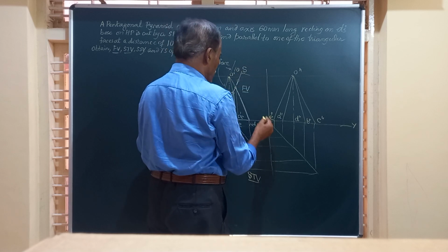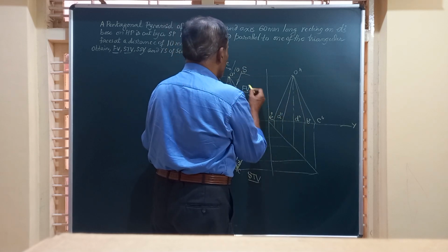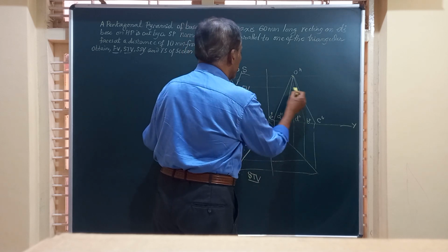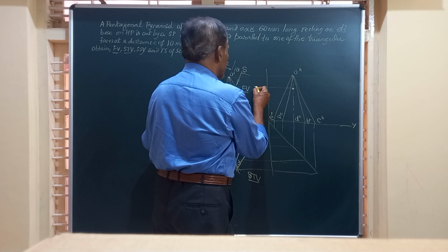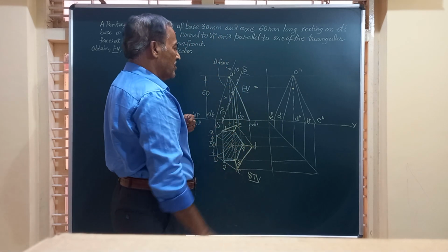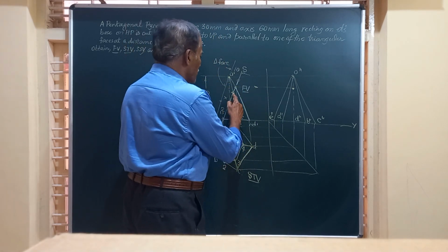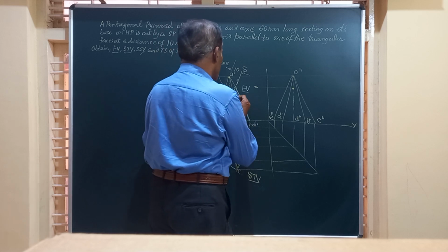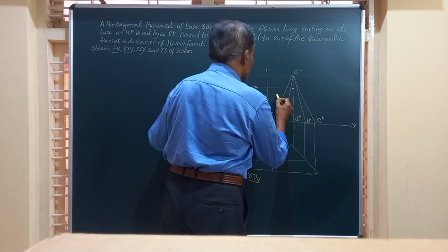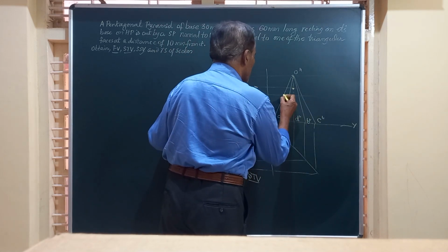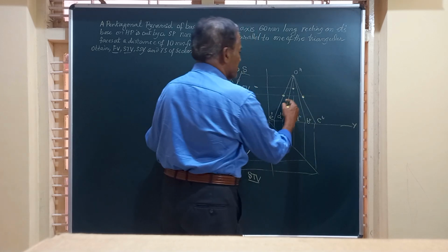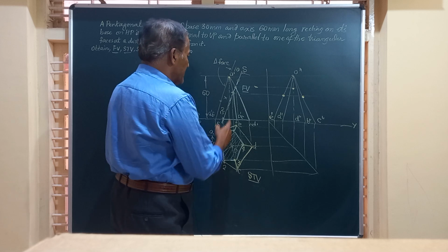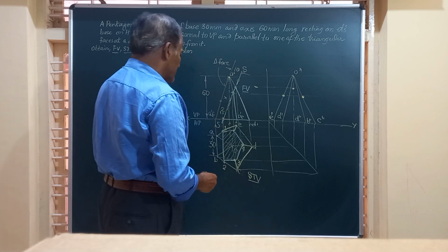This is on OD, that OD is here. So I am going to write a horizontal line till it meets the line, that is slant edge OD. We have got a point. Then here OC and OE are cut here. Just shift the point to OC and OE. This is going to be on the extreme slant edges, OC and OE. Friends, then you got 2 points for the base.